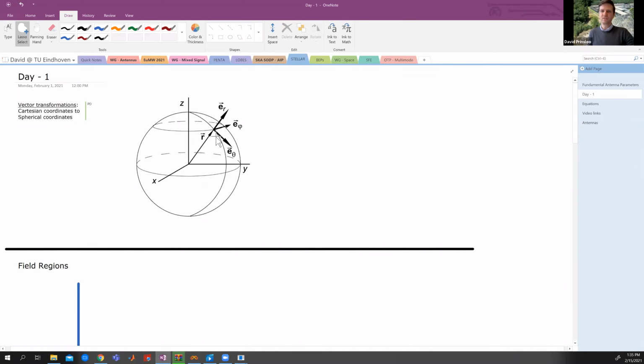It's always convenient to decompose this polarization into 3 orthogonal components. In the spherical coordinate system, we've got our radial component, directed along the direction of propagation. Then if, at the point where you are solving the field, you draw a sphere around it and take a tangential plane at that point, within that tangential plane you've got 2 field components orthogonal to the radial component, which we call the theta and phi components, that we can decompose the electric field into.